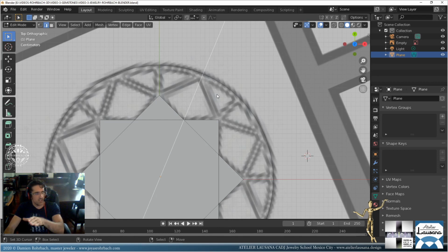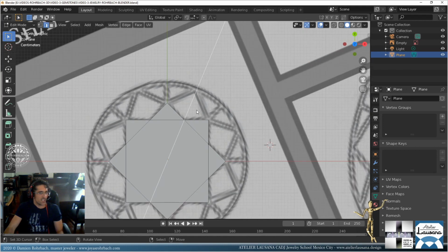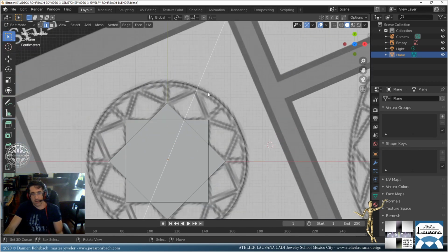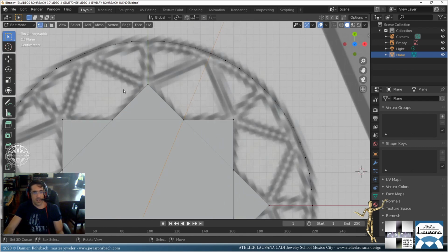It is important to make these verifications from time to time, because even if we're using the snap function and numbers and only numbers, and numbers don't lie, everything should come out perfectly fine. But sometimes things might snap weirdly or badly somewhere, and it's important to check your construction. One way to do that is to create lines or other shapes to verify the general geometry, because obviously vertices must align in each direction. So we're good now.